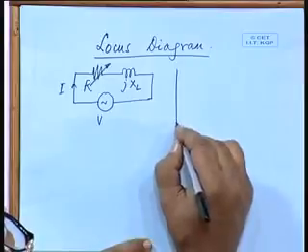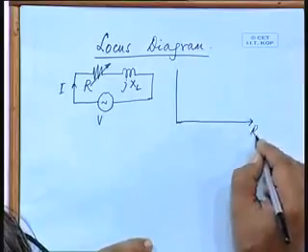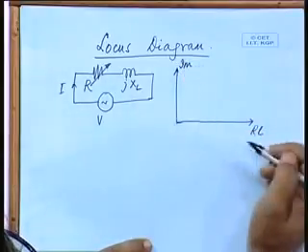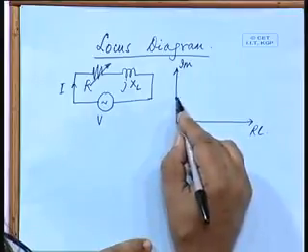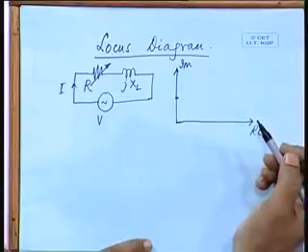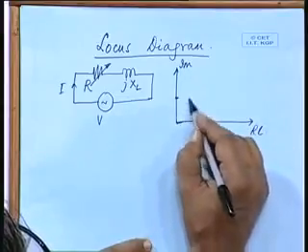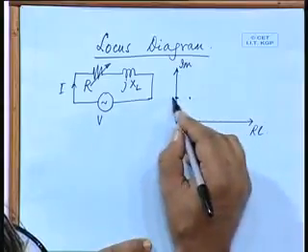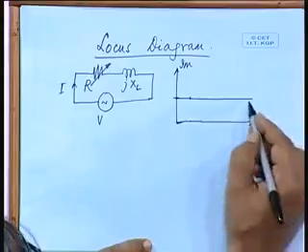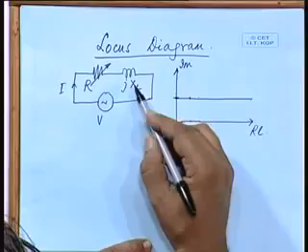So, if we see the impedance diagram, suppose this is the real part, this is the imaginary part, then jXL is fixed, and we are taking different values of R. So, R plus jXL will be, say, R1 plus jXL, R2 plus jXL. So, the impedance varies along this line, is it not? It is minimum when it becomes purely inductive.